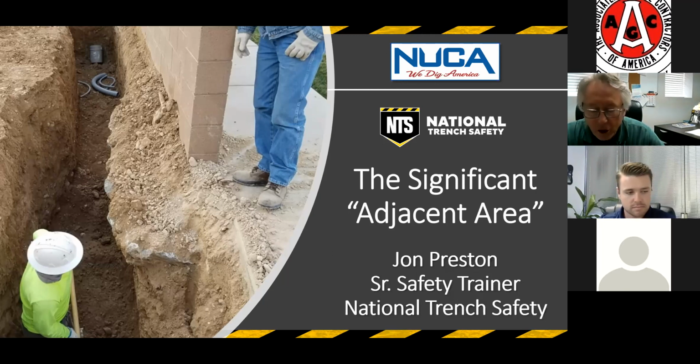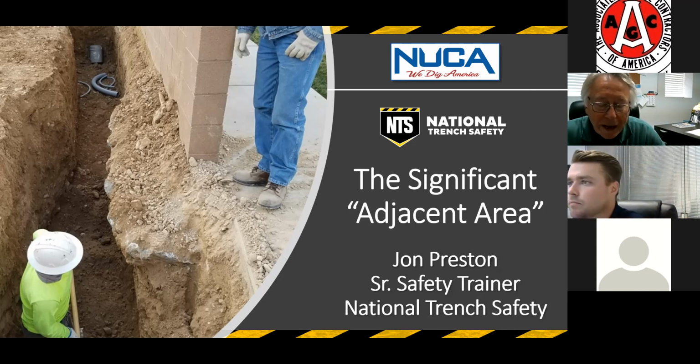Another question for you, John. What is the max allowable distance between a trench wall and the outside of a trench box? Okay, that's a really good question. And the answer is that OSHA does not allow a trench box to have any lateral shift. It's not allowed to move sideways. So OSHA just says no lateral shift.